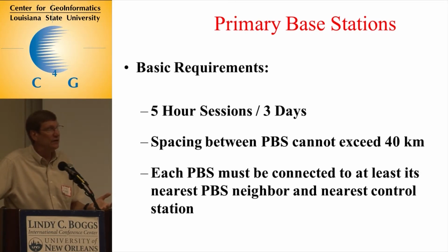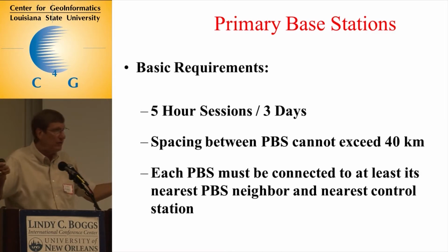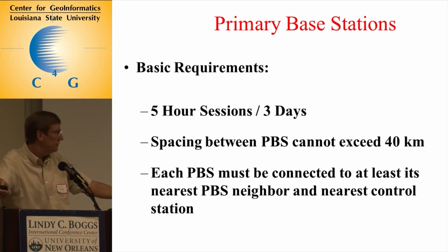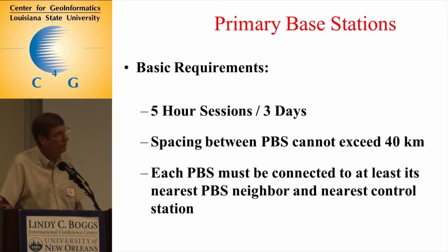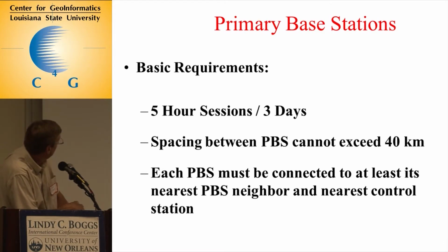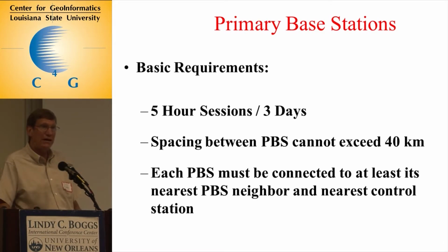I can't emphasize that enough, and I know there's a concept out there that you go out there and you set on this site and stay there for a long time, then you go to the next site, you stay there, and because I know the point positioning, the relative position from the datum to those points, that it should be good enough. And if you're staying there for 24 hours, yeah, you're right. But remember, you're trying to decrease this down to 5 hours now.